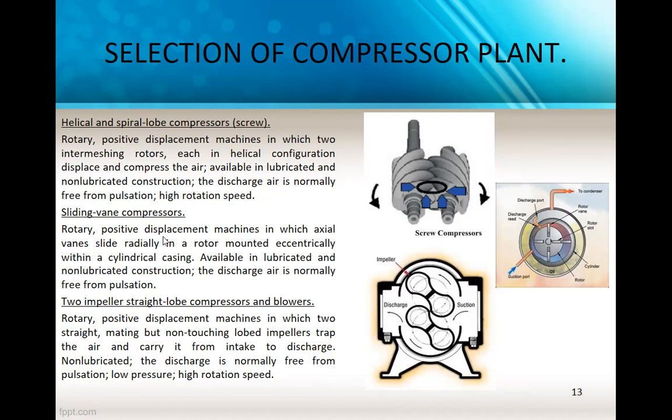Rotary positive displacement machine in which axial vanes slide radially in a rotor mounted eccentrically within a cylindrical casing. Available in lubricated and non-lubricated construction. The discharge air is normally free from pulsation.